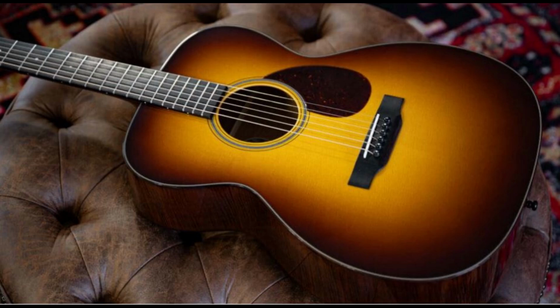These employ piezoelectricity to generate the musical signal and are popular in hybrid electroacoustic guitars. A crystal is located under each string, usually in the saddle. When the string vibrates, the shape of the crystal is distorted, and the stresses associated with this change produce tiny voltages across the crystal that can be amplified and manipulated.